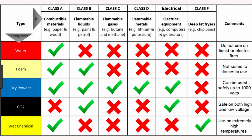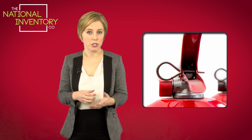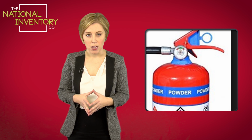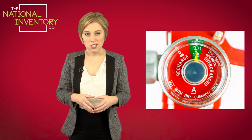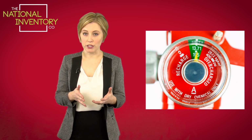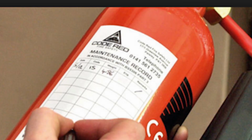If you've decided to have a fire extinguisher within the property, you are then required to maintain it. Most fire extinguishers come with a red pin or a form of plastic pin which blocks the handles from being squeezed together. Once the handle is squeezed together, it triggers the high pressure canister to release the product. So this pin plays a vital part to ensuring that the fire extinguisher is compliant. You also need to have an annual maintenance schedule for your fire extinguisher, in part to ensure that the product is still effective and that in the event of a fire, when you need to use it, there'll be enough pressure. It is not a legal requirement to provide a fire extinguisher under the current legislation unless you have a HMO.